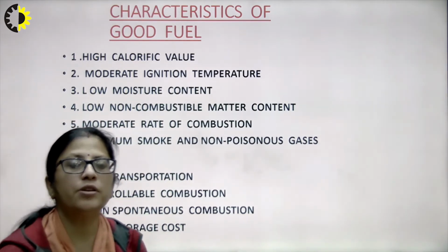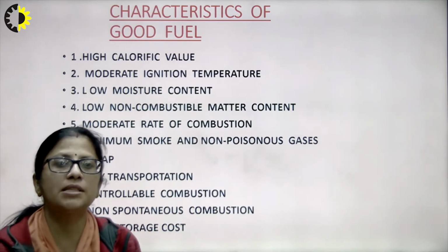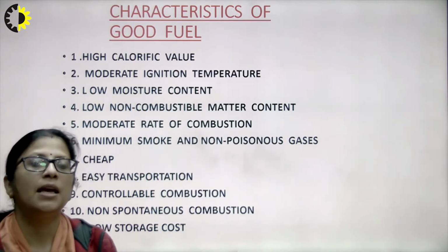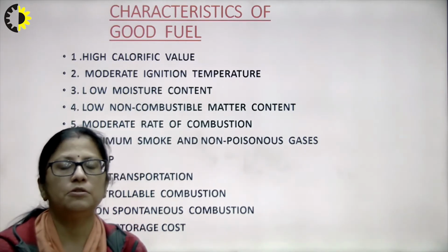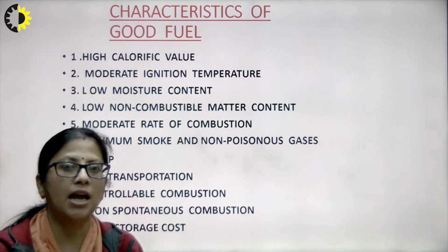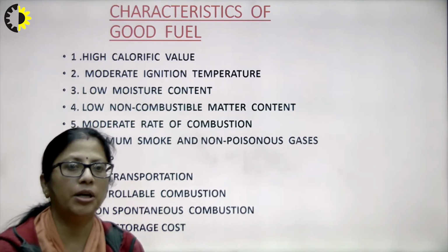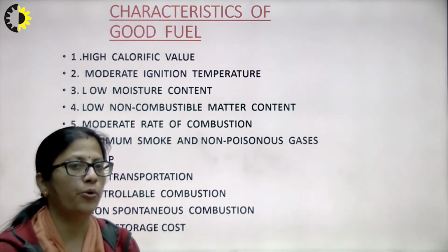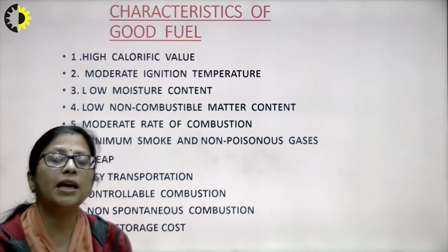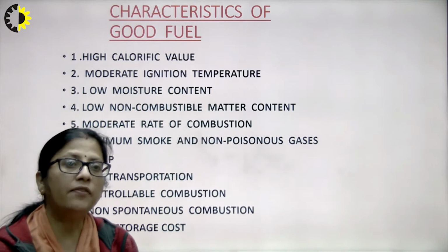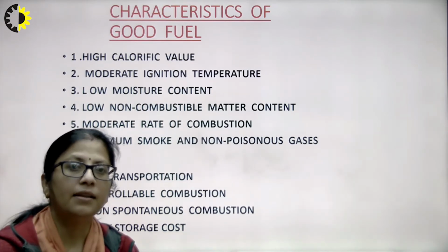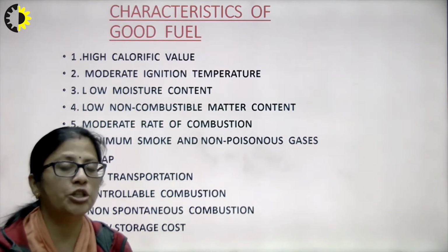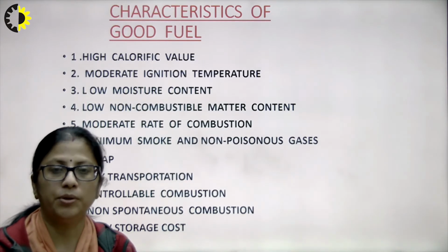Ignition temperature is the minimum temperature at which a fuel starts burning. By saying it should have moderate ignition temperature, we mean that we should provide some heat to the fuel and then it should start burning, and once it has started burning, the entire fuel should burn. If the ignition temperature is low, then in summers the fuel can automatically catch fire. And if the ignition temperature is high, then we have to give a lot of energy input to initiate the process of combustion in the fuel.